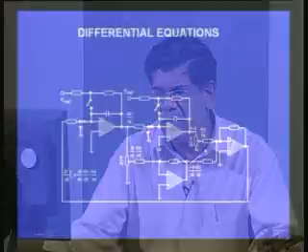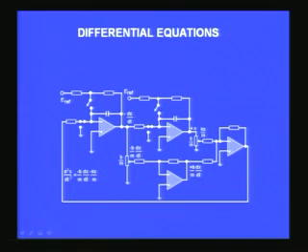and therefore you get the complete differential circuit implemented using these op amps, integrators mostly, and one inverter. This is a summing amplifier, this is an inverter, and these two are integrators. The initial condition can be set by using E reference and things like that, and the greatest advantage of this is that you can understand a real situation if you know the corresponding damping factor, the frequency factor and things like that. You can modify this and try to implement the corresponding system over here and study that very quickly.